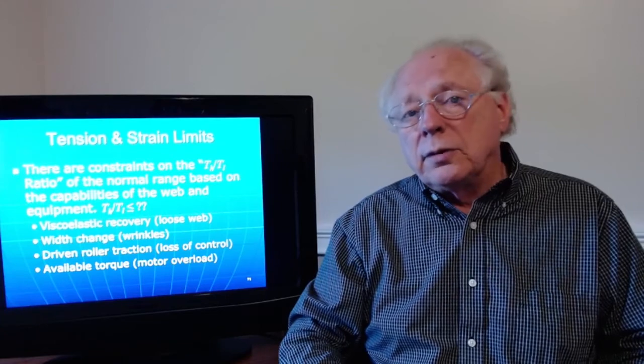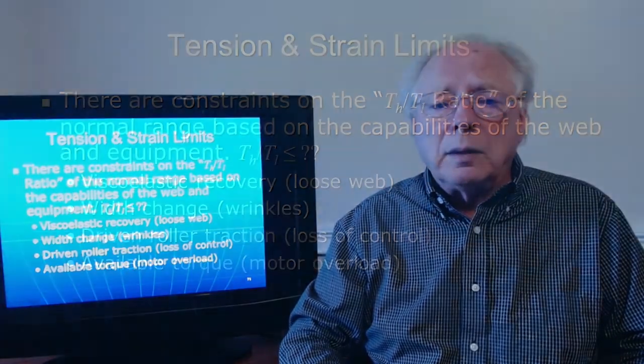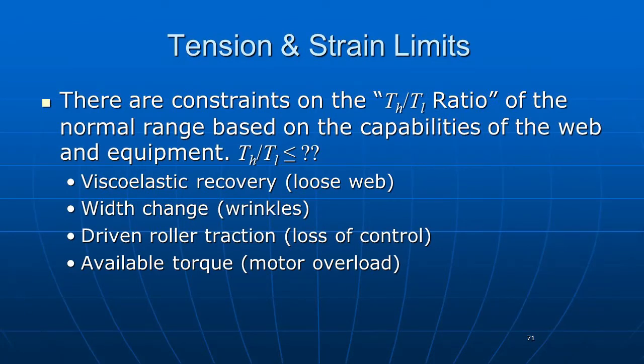And so there are some constraints on the high over low tension of our design range that we have to think about. One is viscoelastic recovery. When you stretch a web and try and let it recover, it doesn't instantly recover to its original relaxed length. It takes some time to suck itself back up. We can't typically take huge tension drops over driven rollers and expect the web to fully suck itself up. My experience with a lot of webs is they'll typically do about a 6-to-1 recovery.